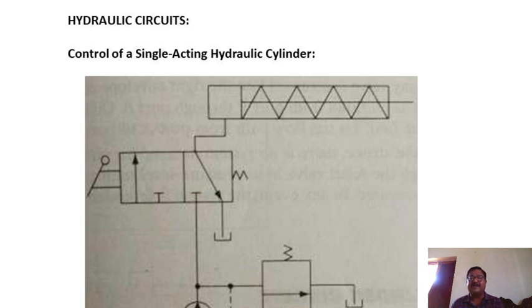It includes the oil's viscosity. Viscosity means thickness of the oil. If the viscosity of the oil is too high, then the pressure needed for the transfer is more, so the oil will not flow freely. If the viscosity of the oil is too low, if it is too thin, then the oil may squeeze out. Other problems of the hydraulic circuits may occur, as we all know that.